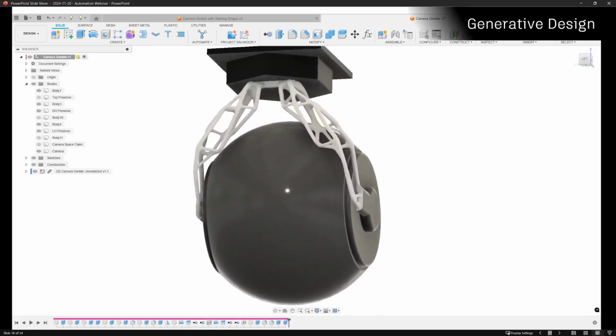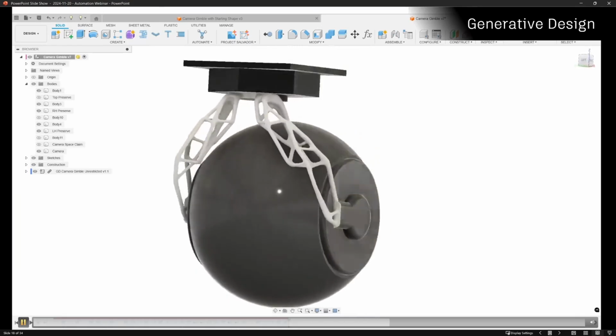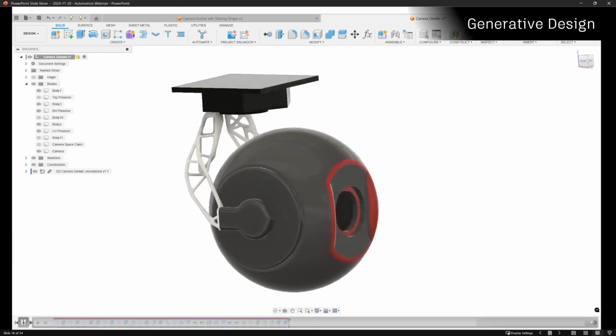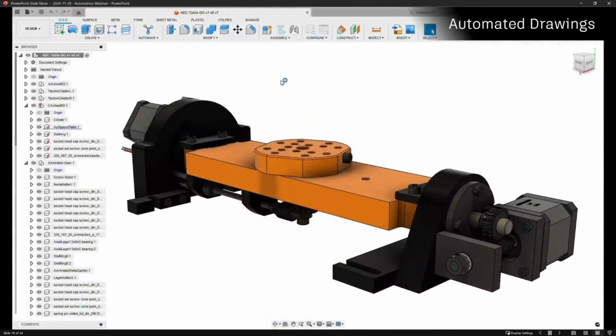Plus as well, I just want to check it over to make sure it looks structurally sound as well for anything I might have not encountered. Quite often you get what's called a phenomenon called bird bones, where it will make a very thin structure, which, okay, that contributes to the whole design, but of course if we drop that, that's probably going to snap as well. So there's still a little bit of human intervention to be made at the end as well. But a fantastic automation and AI tool to generate results that you more likely would never have thought of yourself. And we're seeing that get used more and more across the world.